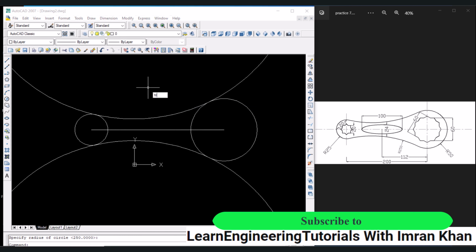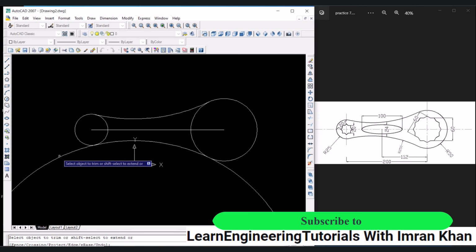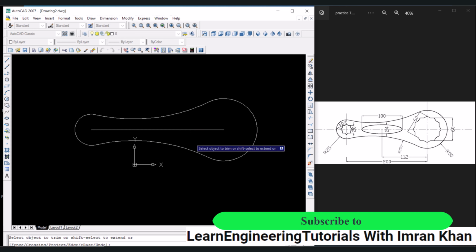Now we'll perform trimming, so TR, enter, click over here, click over here, click inside, here and here as well. Now press escape. Now we'll draw the ellipse, so click on the ellipse icon. From this end, go in the negative direction, and we have to give the center of the ellipse as -112. Press enter, so it has taken that center.